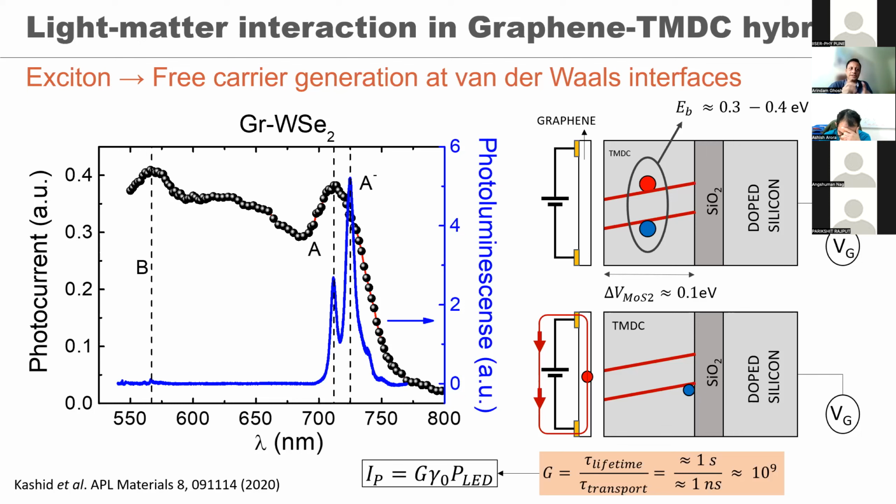Right. So let me separate out your question. First of all, what you see in your chalcogenide-based system, the dark current is low. You're absolutely correct. But that is the current through the chalcogen layer, correct? So that is determining your dark current. Whereas in the devices here, the dark current is determined by the resistance of graphene, which is orders of magnitude smaller than the resistance of the chalcogen layer. So if you want to look at the photo response of an individual chalcogen layer, for example WS2 or MoS2, there your dark current is limited by the conductivity of the chalcogen layer.